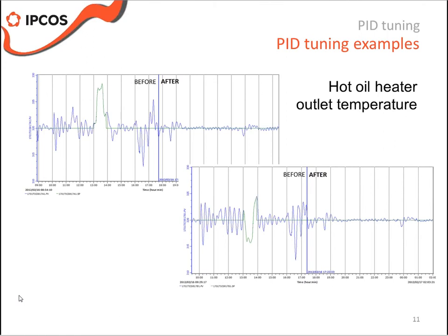The type of problem here is to do with users of the hot oil, the fact that they are changing all the time in terms of the amount they use, as well as the set points that are set on the process side. Hence, the return temperature of the hot oil is always changing. So you get a lot of disturbances in the system. And what we did was we did a small test in this area where the loops were put in manual.